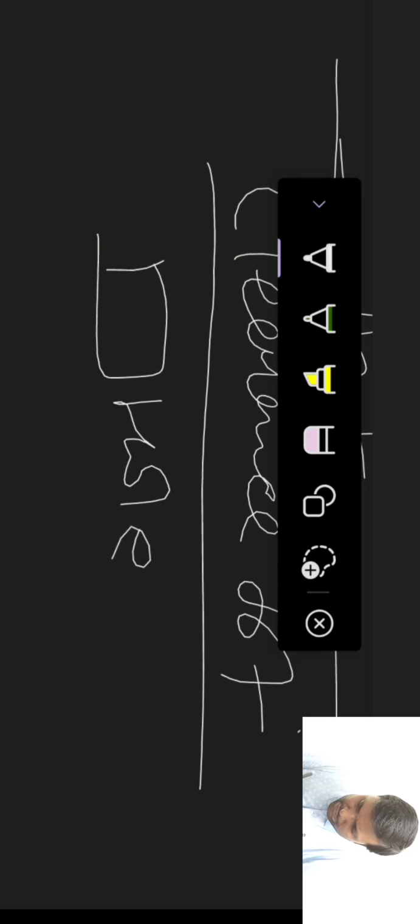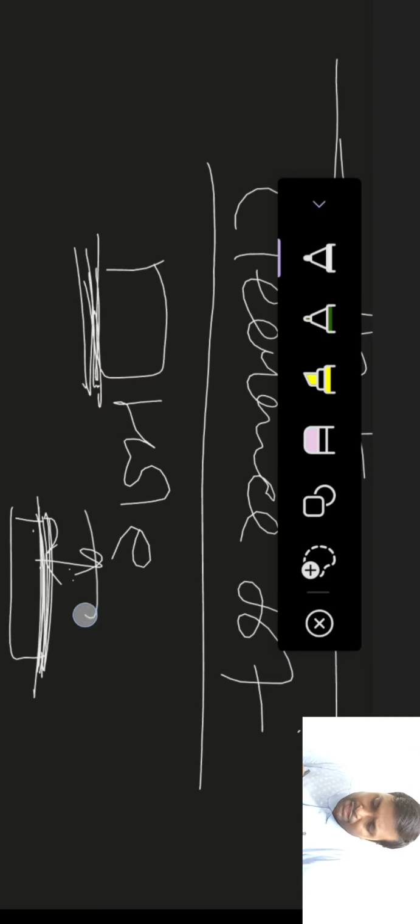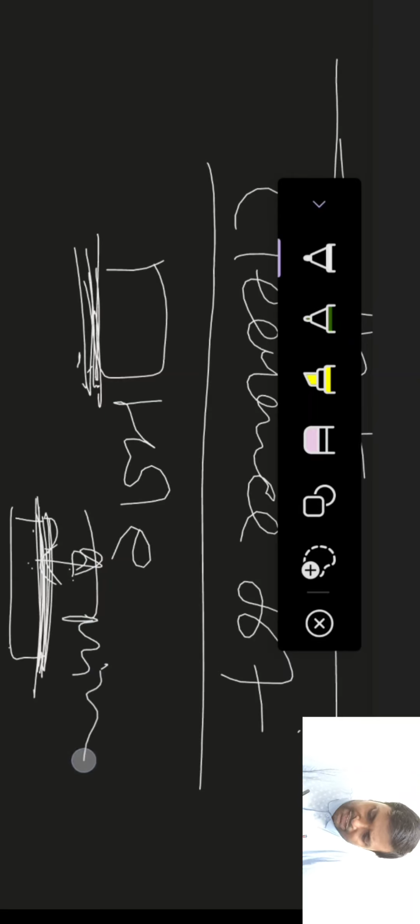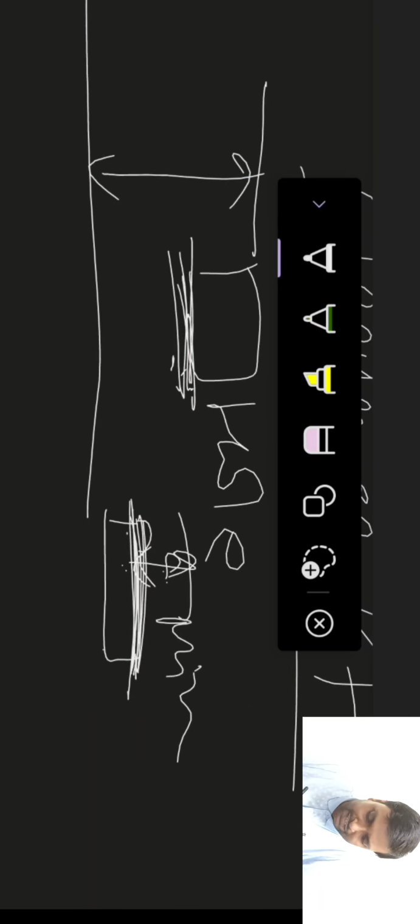You are seeing that this is the smallest diameter of the hole and this is the largest diameter of the shaft. This largest diameter is below the hole, so there will always be clearance. This is the gap, and this largest shaft diameter is less than the smallest hole. For all other pairs there will be a gap or clearance, and this is the case of the clearance fit. This gap is the minimum, known as minimum clearance. And when the hole is largest and the shaft is the smallest, this gap is known as maximum clearance.